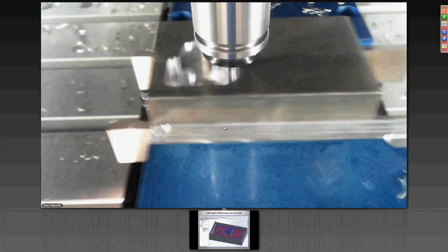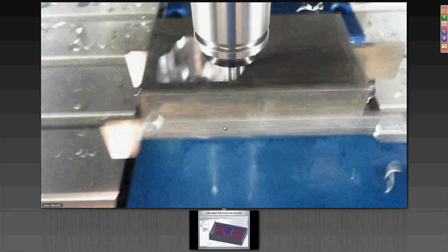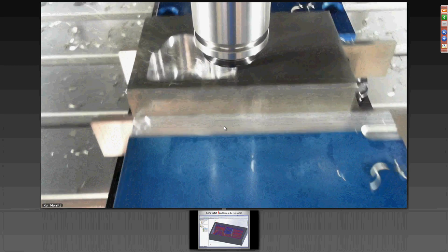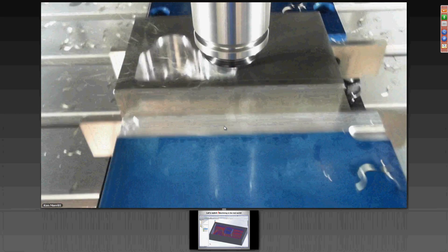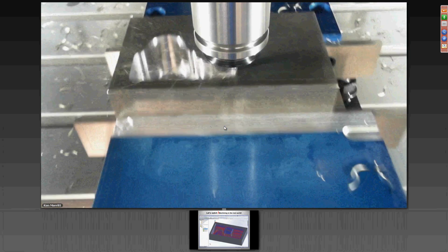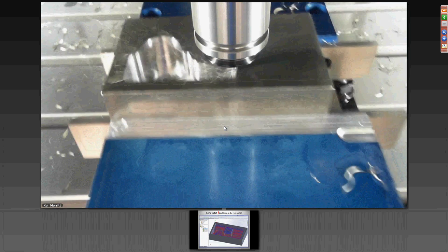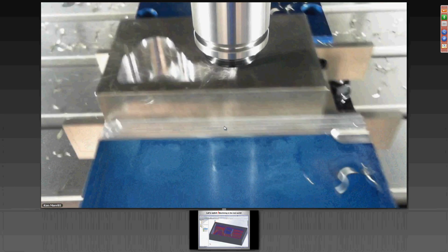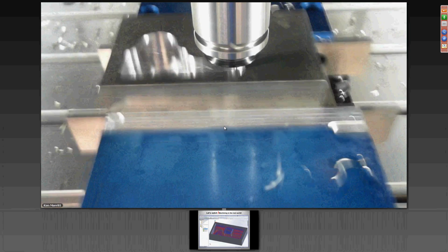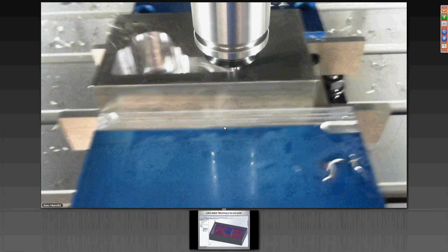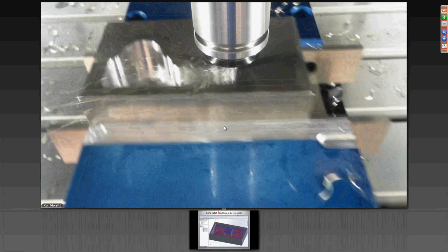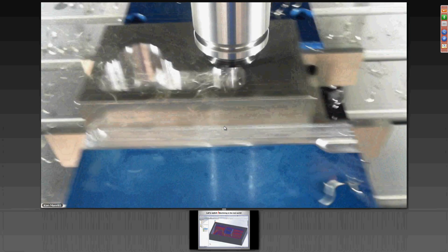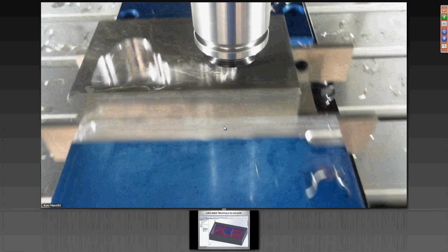When it's changing the angle like that, at the maximum angle we're running at the programmed feed rate in the wizard. But as the cutting angle comes down to afford the morphing, we actually increase the feed rate so that we sustain a constant chip thickness at the angle of contact. That's one of the things that's very different about how we're programming versus some of the other systems on the market that may look similar to this. Almost everybody else that I know of, and I don't know of anybody doing it our way, is working with chip load. In other words, the thickness of the chip at the 90-degree quadrant relative to the direction that the tool is traveling. We're actually working with the chip thickness at the contact point where the tool is actually cutting.